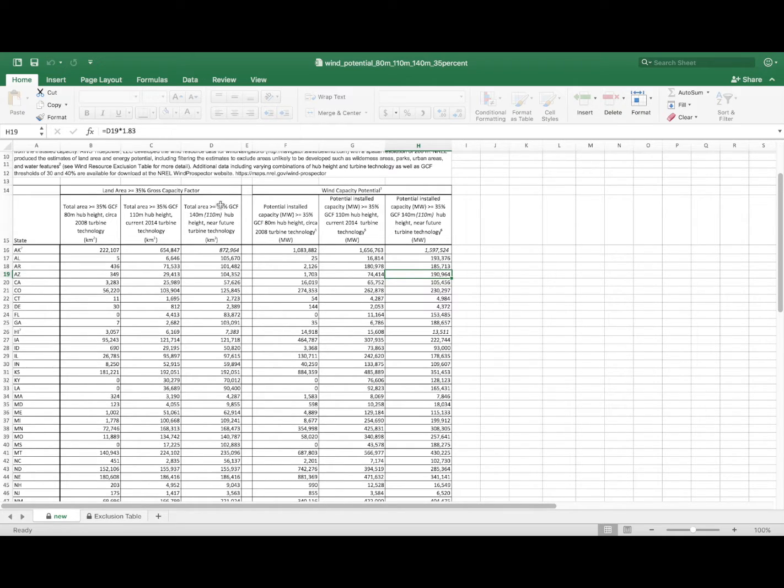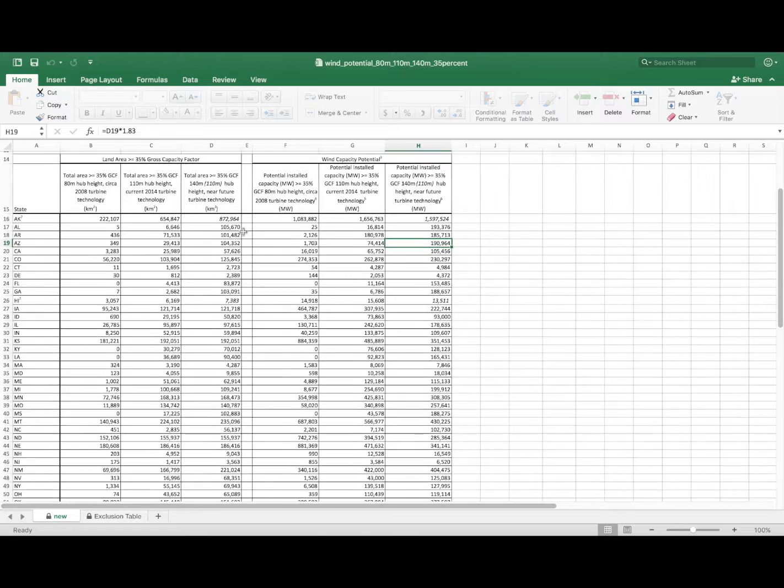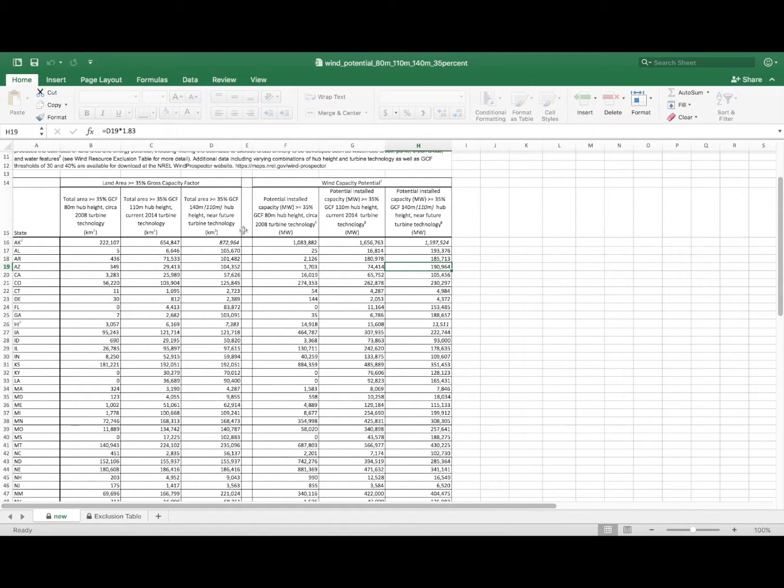What capacity factor means, I talked about it a bit in class, but it's really important to understand. It means that if you have a wind turbine that's rated at 2 megawatts, 35% of the time it's going to be operating at maximum capacity. And in the real world, this is probably going to be like 50% of the time it's operating at 60% or 70% capacity. So very rarely are wind turbines ever going to produce their whole capacity, but a certain percentage of the time they won't be operating, and a certain percentage of the time they will be operating at maybe 50% capacity. So the capacity factor is very important to understand.